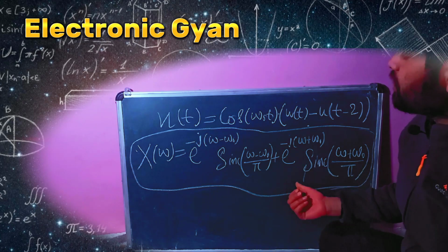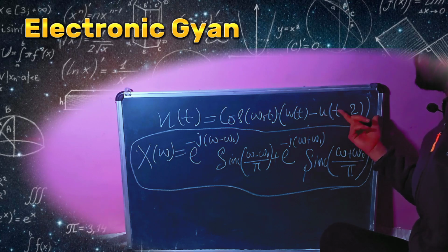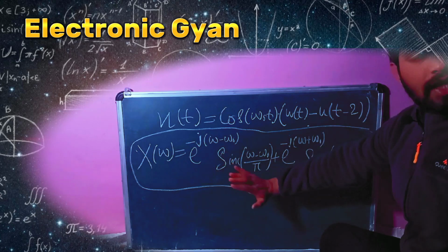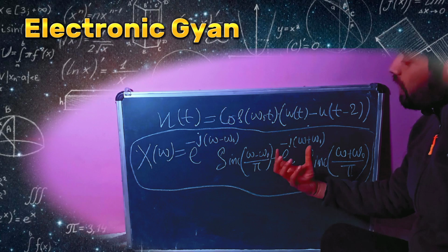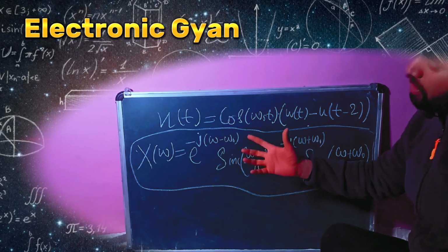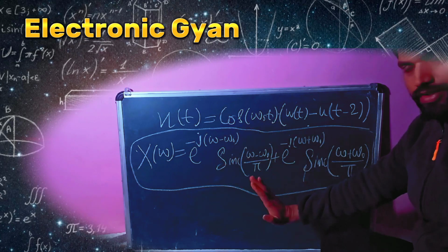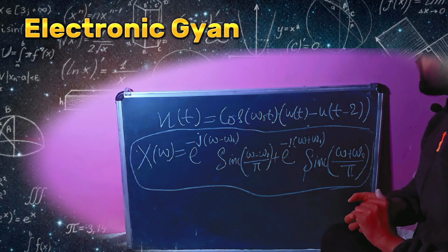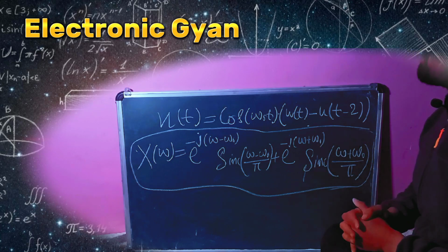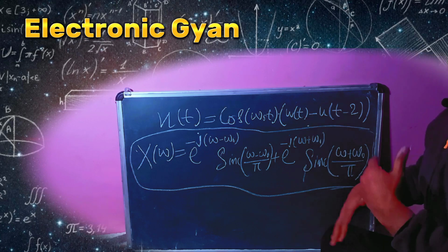In this way we can find the Fourier transform of the signal. Whichever the unit step functions and however much shifting there is, we plot that signal, and then we recognize that it is a shifted rectangular signal. Then we apply the shifting property in the Fourier transform. This is the way to find the Fourier transform of a sinusoidal signal multiplied by a shifted unit step.